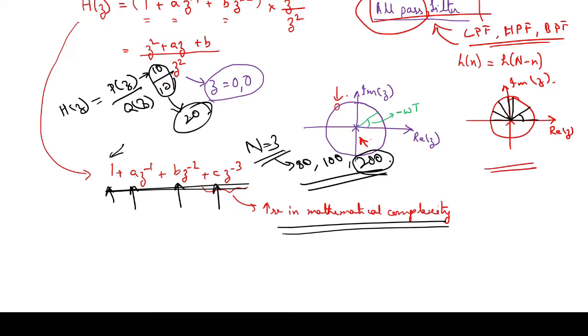However, usually while we go for the designing of the IIR filter, we hardly go beyond the order of 3. So you can see the mathematical complexity is much lower in the IIR filter. Even though if you see the method of calculation of those filter coefficients, it would be quite complex. But the implementation part will be a bit easier.